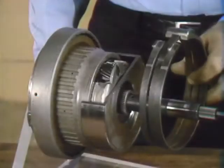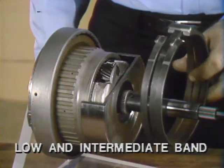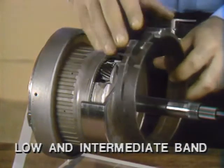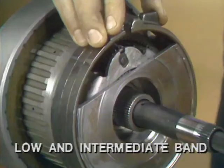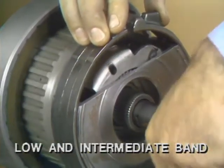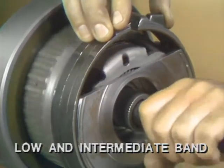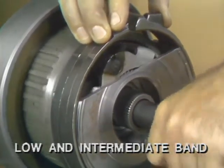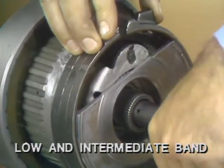The last holding member for the gear train is the low and intermediate band. The band also is mounted stationary in the case, around the drum, which is part of the forward sun gear assembly. And so when the band is applied in first and second gear, the forward sun gear is held stationary. With the sun gear held stationary, the long pinions are forced to walk around the sun gear.